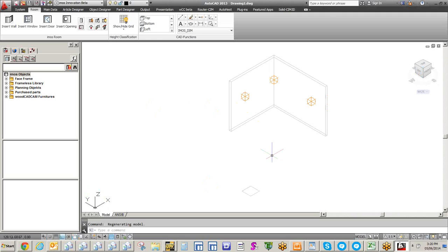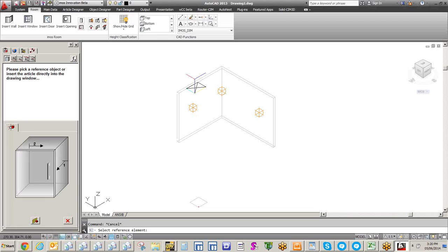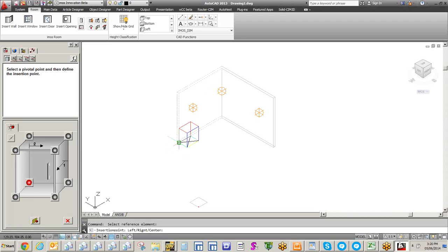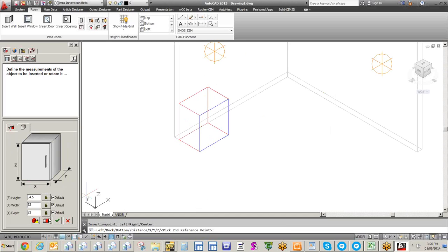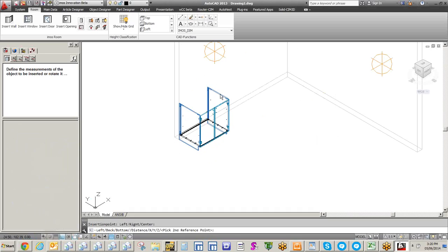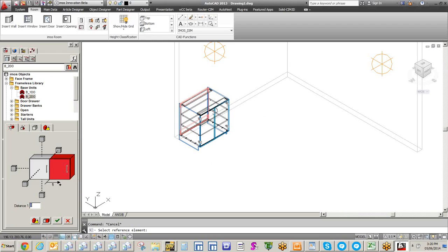Of course, you can add additional openings, make walls follow polylines, whatever it is that you want to do. Working from our library of products, we just begin by selecting a product, in this case a two-door base, and I'll select on a wall where we might want to place the product. Notice how easily it can slide into any position or even change directions along an opposing wall. We just give this an insertion point that we want it to work with, and I'll select the multiple button in case we want to put in more than one of the same product.